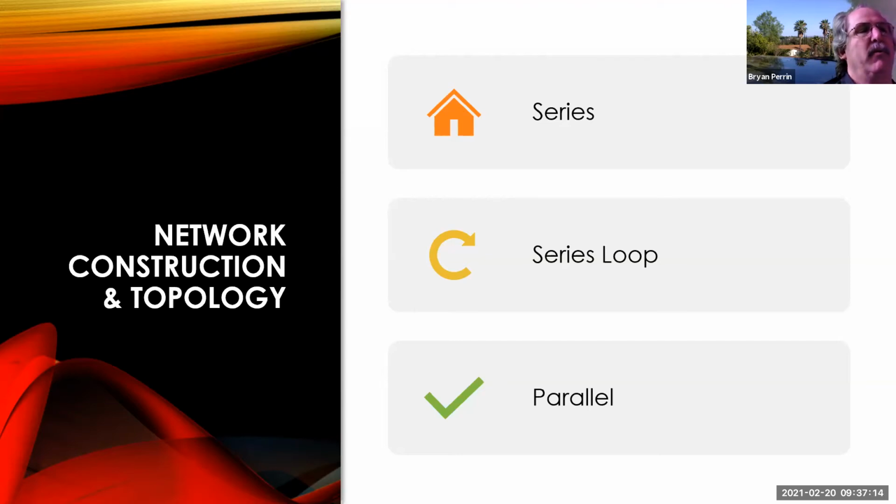And then a parallel network. This is where each module has its own leg from a central location. And these are great for diagnostic testing. Parallel networks are some of the easiest to diagnose because there's a central point where all the modules plug into. And so then if I think I have a short or something like that, I can go to that central point. I can unplug stuff. I can test each of the legs as I pull all the modules out like I would on a daisy chain system. So each of these has advantages and disadvantages.